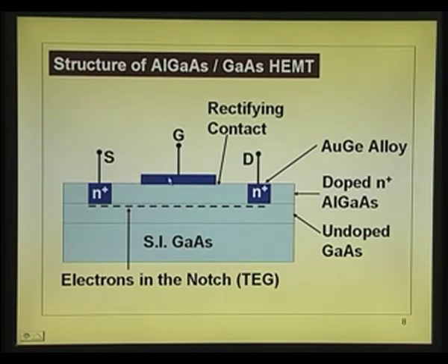So, put a gate here so that you can deplete the entire layer. I will come back to those more details after. Right now, I will keep you in the perspective how you are avoiding that current transport through that. You have a metal semiconductor rectifying Schottky barrier. So, you can see the Schottky barrier haunts us everywhere now.